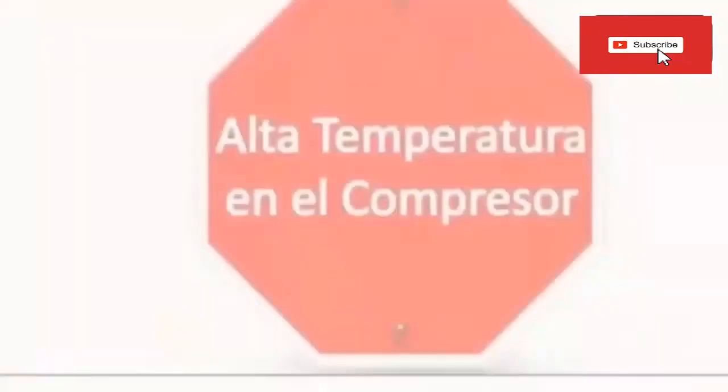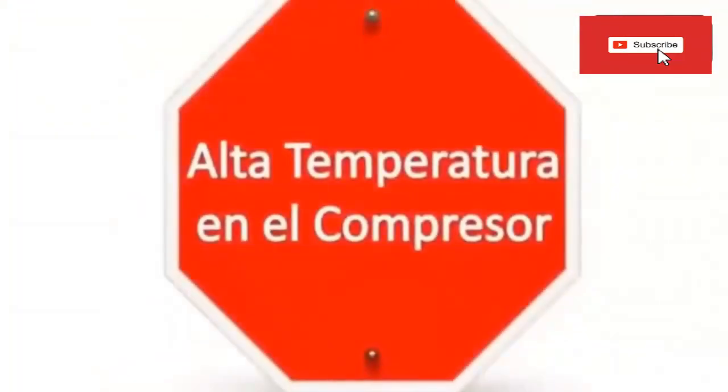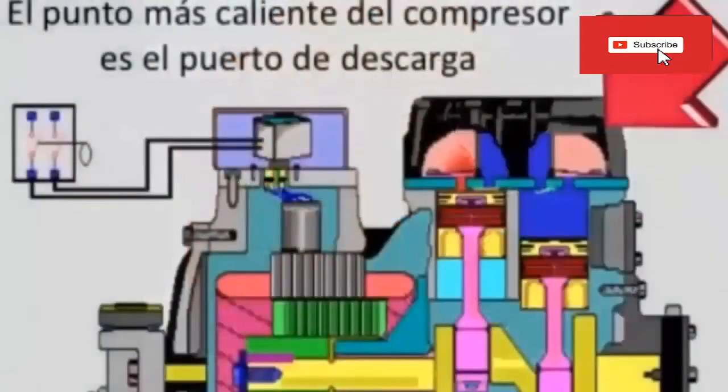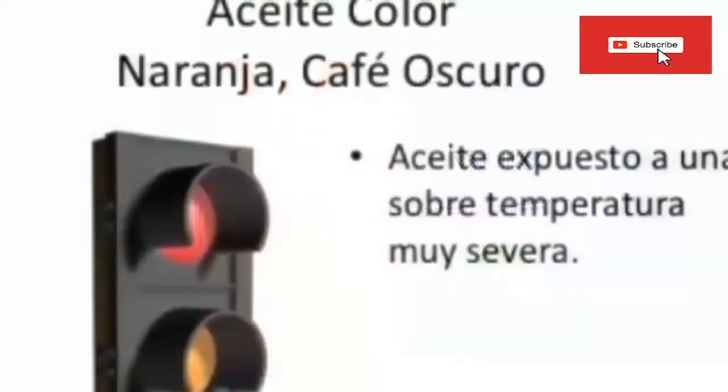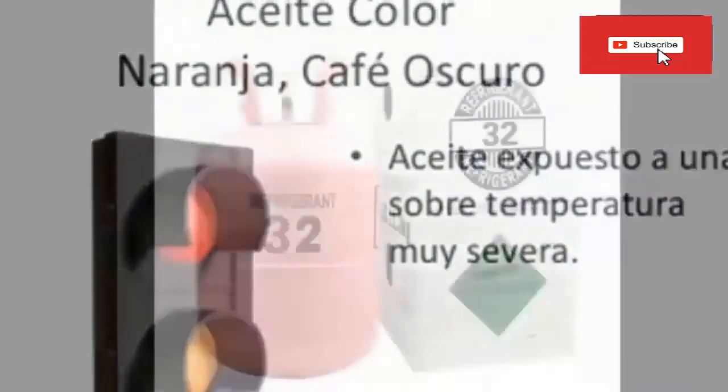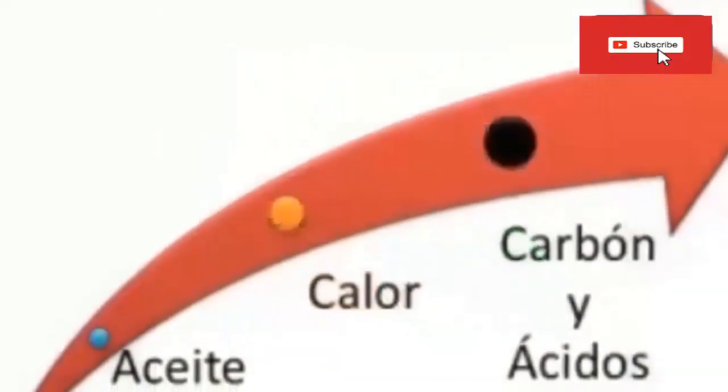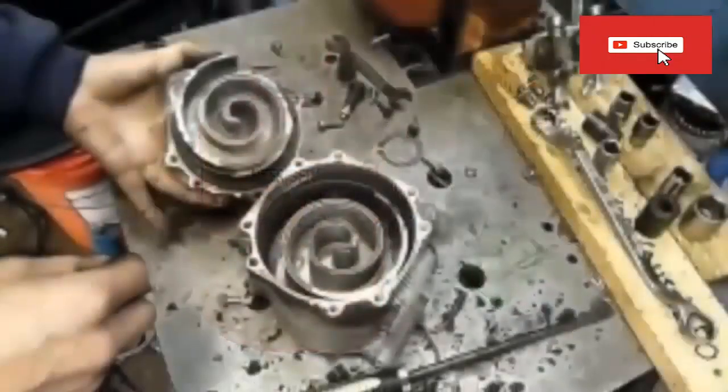However, this is not all we need to know. There is something very important that not many mention. I'm talking about the discharge temperature that the R32 refrigerant has. Remember that the compressor discharge temperature is the most critical in the refrigeration cycle because it is the highest temperature in the system and must always be within the ranges that the equipment compressor and its lubricating oil allow. This value is higher than the condenser temperature, because the refrigerant R32 is in a superheated vapor state. If a compressor works with higher discharge temperatures than it was designed for, it will quickly fail.